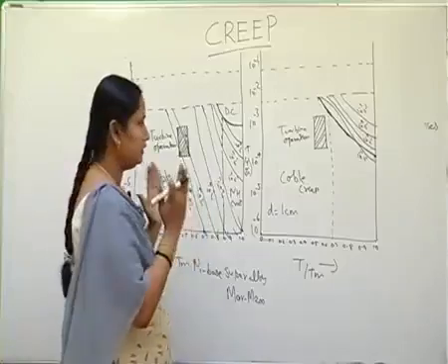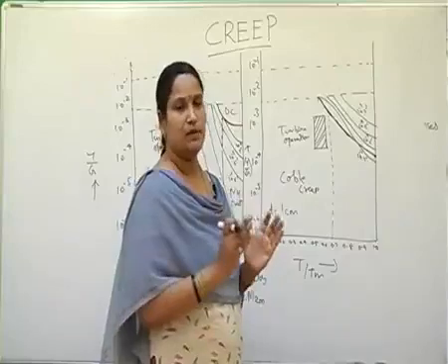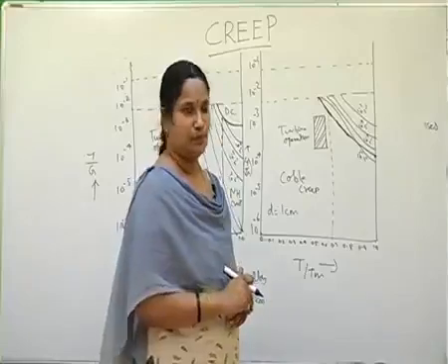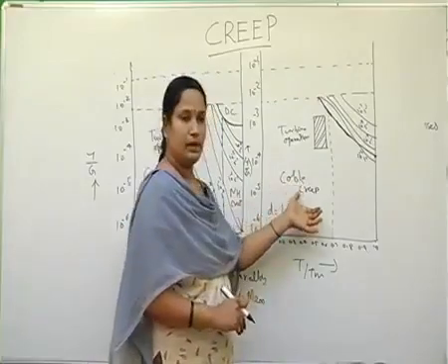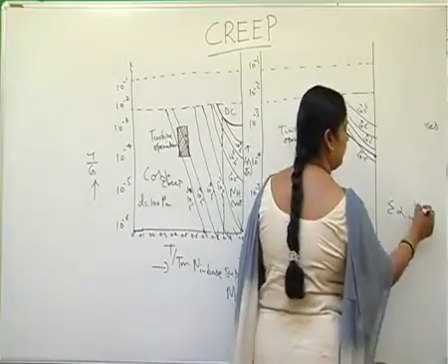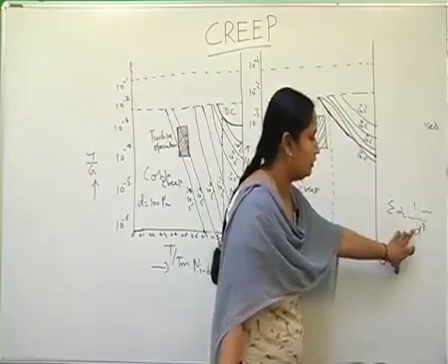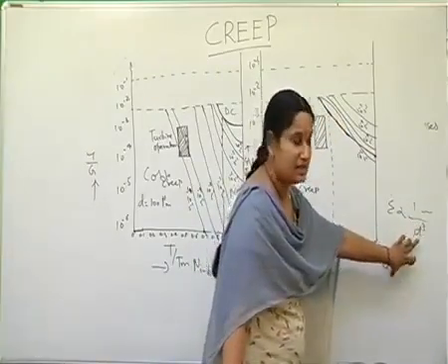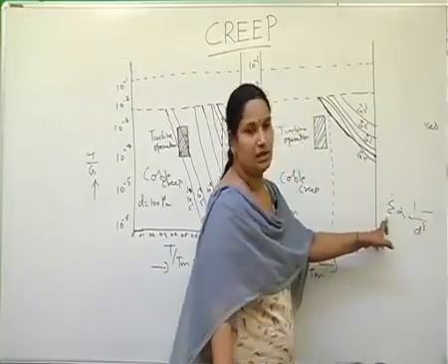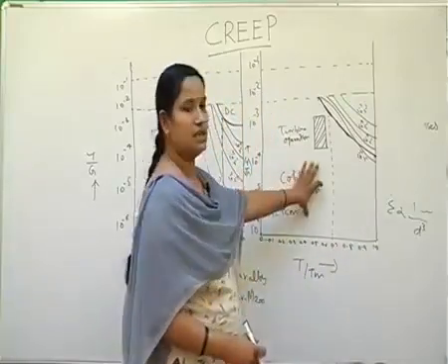So simply by knowing the dominant deformation mechanism for the particular operational stress and temperatures, one can lower the creep rate. Coble creep rate, in that expression, with a number of constants, is inversely proportional to d cube, the cube of the grain diameter. So by increasing the grain size, the creep rate is lower. Simply by shifting to a coarse grain size, the creep rates are lowered.